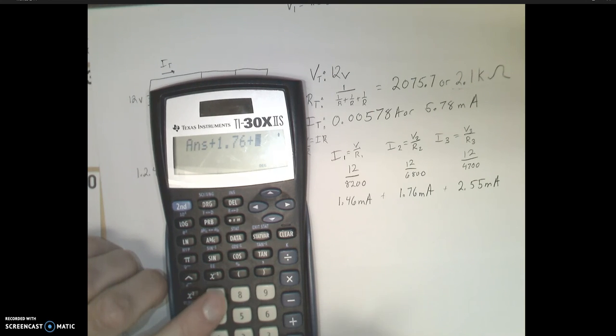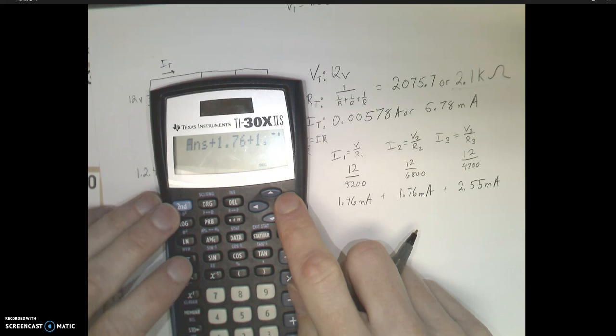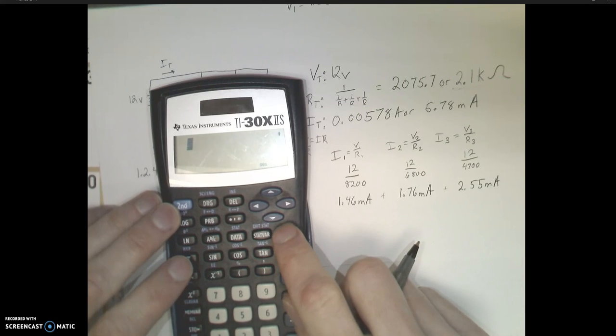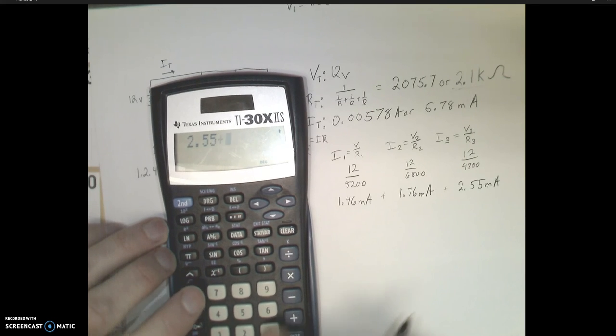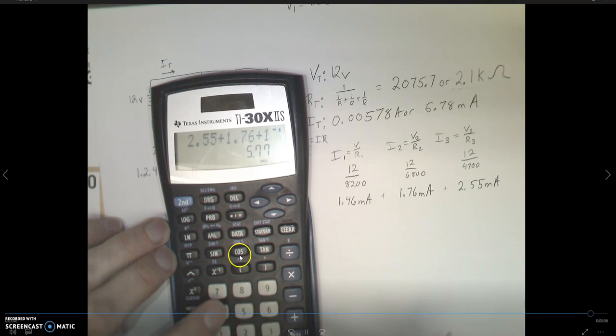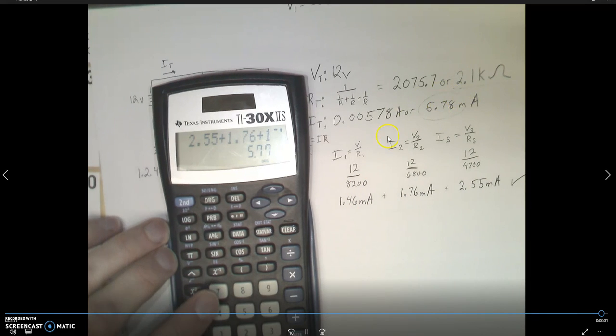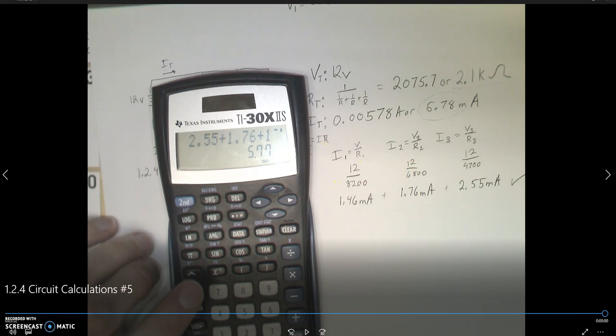We have our different laws. The sum of all of the individual component amps should equal to the total. So if we find and add up those 3 sets of milliamps at each resistor, we add those together, we should see that the total of those 3 is equal to the total for that whole system. So this plus that equals that, gives us our total. We know we did things right. We can check that off the list.